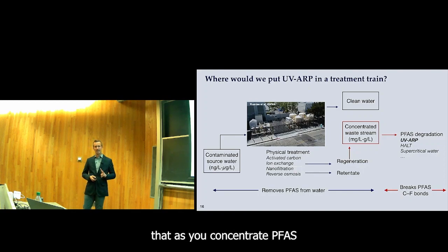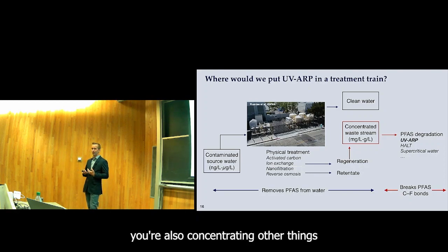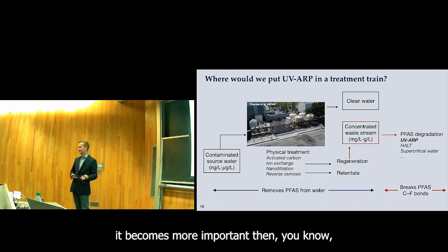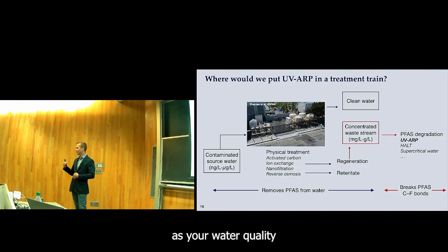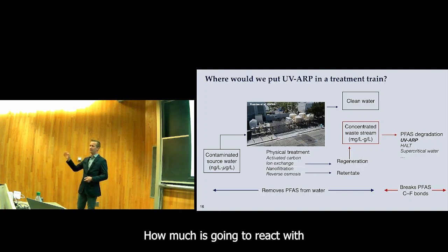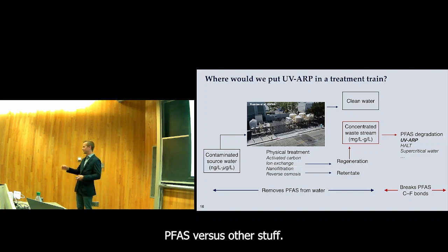The other is that as you concentrate PFAS, you're also concentrating other things in the water, right? DOC, nitrate, alkalinity, all these things. And so it becomes more important, as your water quality gets worse, so to speak, that you understand how much aqueous electron is being formed and where it is going. How much is going to react with PFAS versus other stuff.